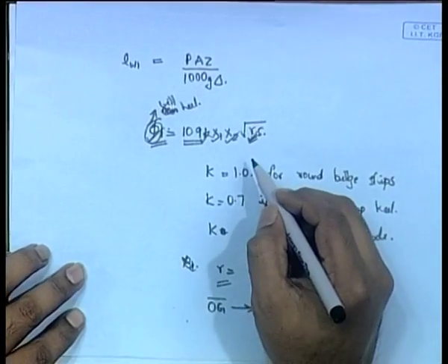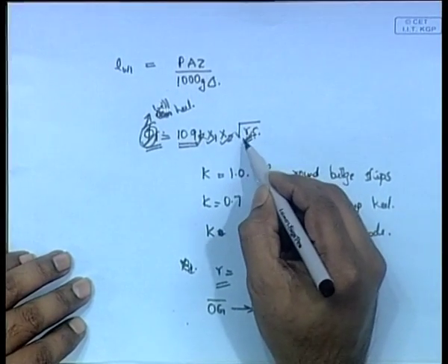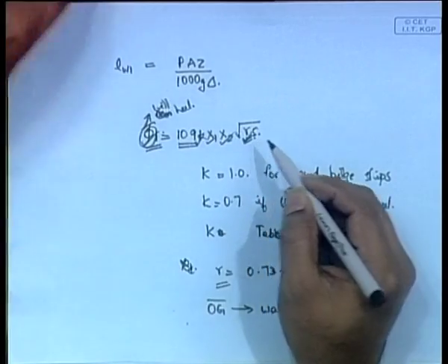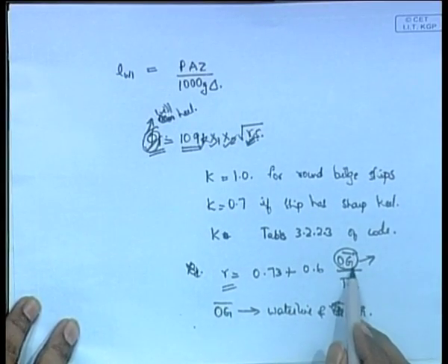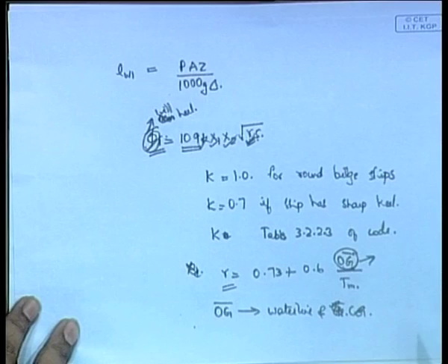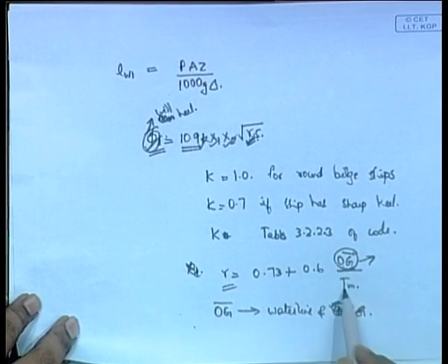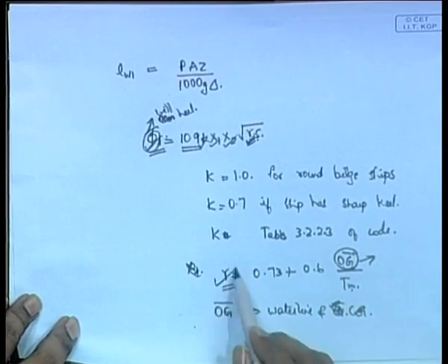So, now this is the way. So, now you have S, R, you have already been given the equation here, R is this. So, we need to calculate OG next. OG is the distance between the waterline and the center of gravity of the ship. So, provided you know the height KG, which is given as you have seen in these problems, KG is given. So, once you have the center of gravity of the ship, you can find the distance up to the waterline, and once you have that, you have the draft also, you can get R.